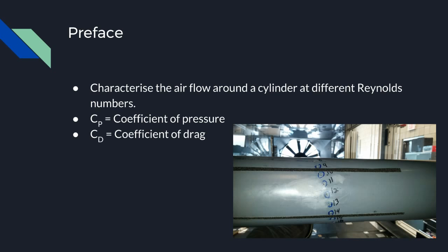After running and collecting data for each velocity, a sandpaper strip was then placed on an optimal angle on the frontal area of the cylinder in order to trip the flow and re-energize the boundary layer to keep the flow attached around the cylinder longer.